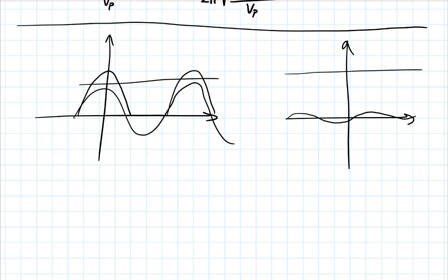And you will quite possibly encounter many examples of trying to apply a filter when you're doing a software project. For instance, if you apply a filter to an image, let's say you have an image and you're trying to get rid of noise. You might apply a filter, meaning you're trying to get rid of a lot of the high frequency variations because you know that that's just adding noise to your image. And you will keep components that are not spatially varying too much because you know that, let's say, your image doesn't have features that change every pixel, right? So this is very, very broad. And this is just one example of that.